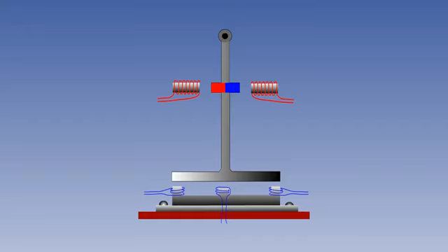There are various different forms of accelerometer, but a popular early model was the pendulous E and I bar type. The E and I bar is a fairly common form of transducer, and is also found, for instance, in the servo-assisted altimeter, which you have already studied. The E bar is made of a material with a high magnetic permeability. This means that it responds by producing a high magnetic flux density in proportion to the inducing field, and responds rapidly to rapid changes in the inducing field.